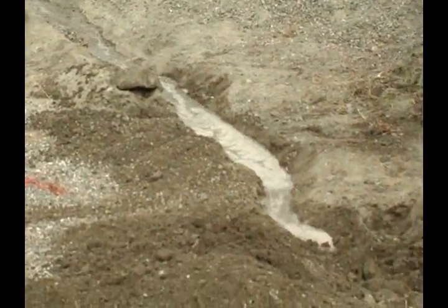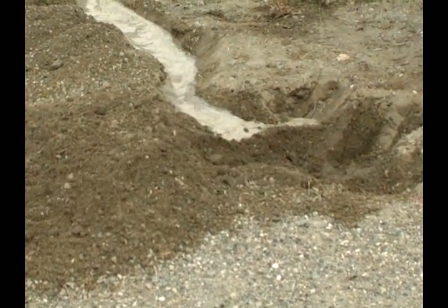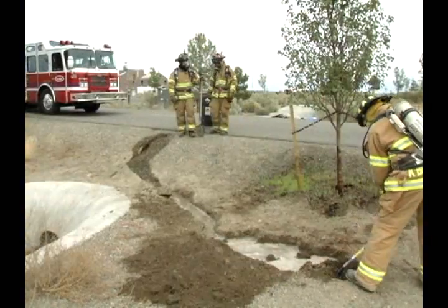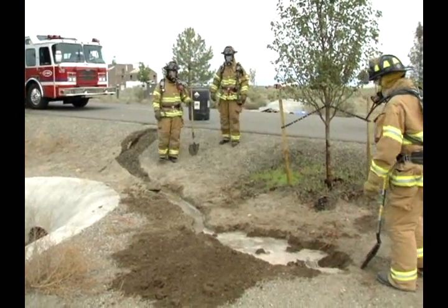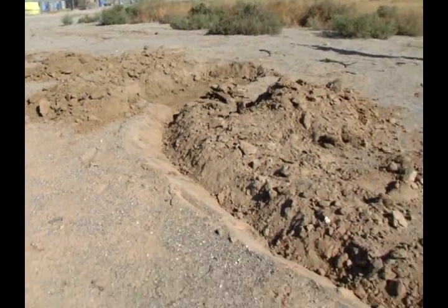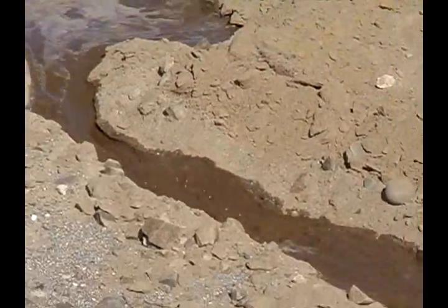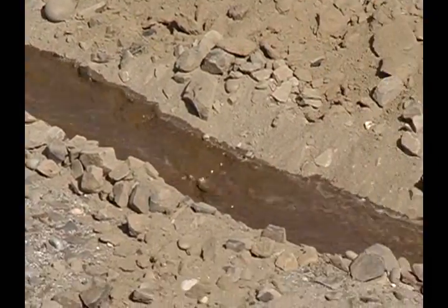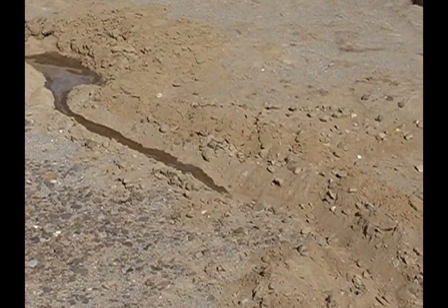The diversion dike should be constructed so that it will control the direction of the spill, yet not be so large and complex that it strains the physical limitations of the firefighters. Determine the angle, height, and length of the diversion dike according to the speed and volume of the spill. For fast-moving spills, an angle of 60 degrees or more will be needed to slow it down.